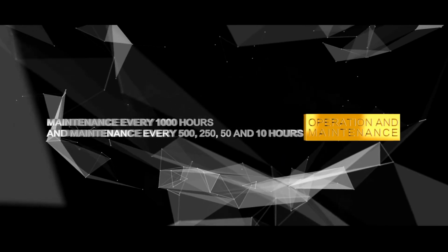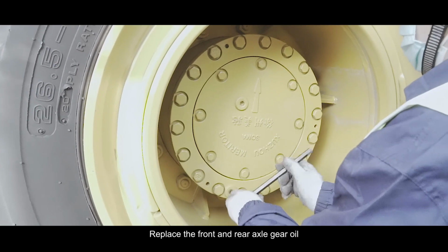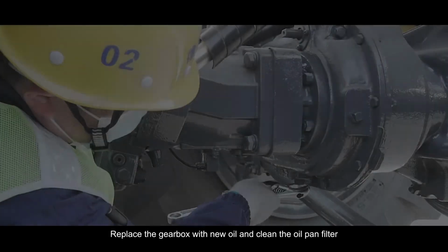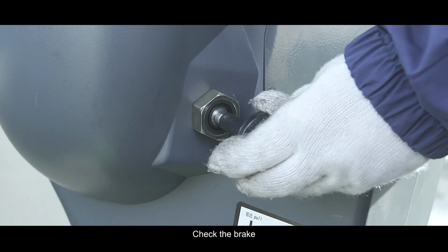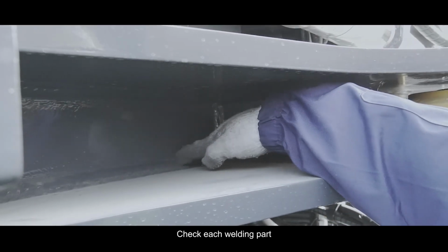Maintenance every 1,000 hours, together with maintenance every 500, 250, 50, and 10 hours. Replace the front and rear axle gear oil. Replace the gearbox with new oil and clean the oil filter. Change the working oil of the hydraulic system and clean the oil filter of the oil tank. Check the brake. Clean the oil filter of the diesel tank. Check each welding part.